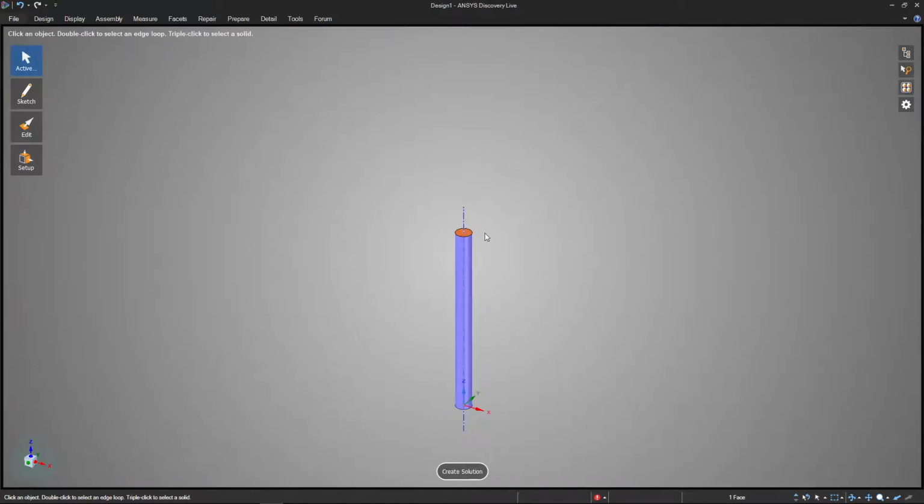Now we're going to put a cube of aluminum on here, so I need to sketch a square and then pull that up 3-dimensionally. So going back to my sketch menu, I'm going to find the square tool, and a square is a type of rectangle, so we'll begin with that. Whenever you go to sketch after you've got something 3-dimensional, you usually have to define your sketch plane. That's the first click. So I've already got the very top of my circle here, which was selected when I went for that option, being defined as the thing that I'm sketching on. You can always change that using some of the navigation buttons here.